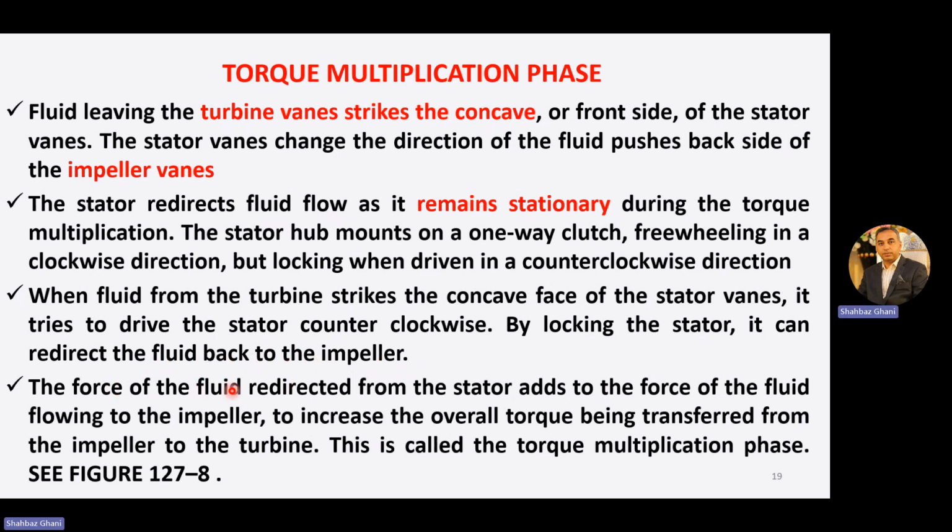The force of the fluid redirected from the stator adds to the force of the fluid flowing to the impeller, to increase the overall torque being transferred from the impeller to the turbine.